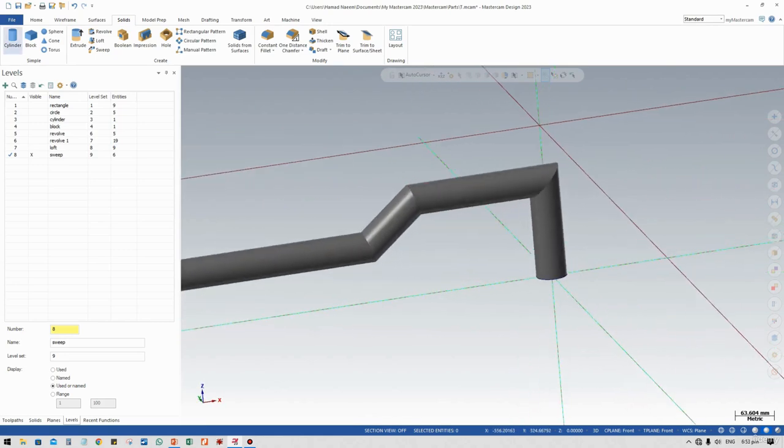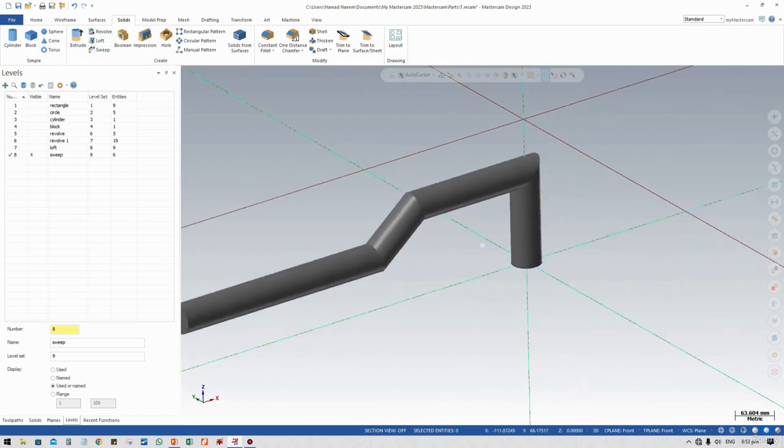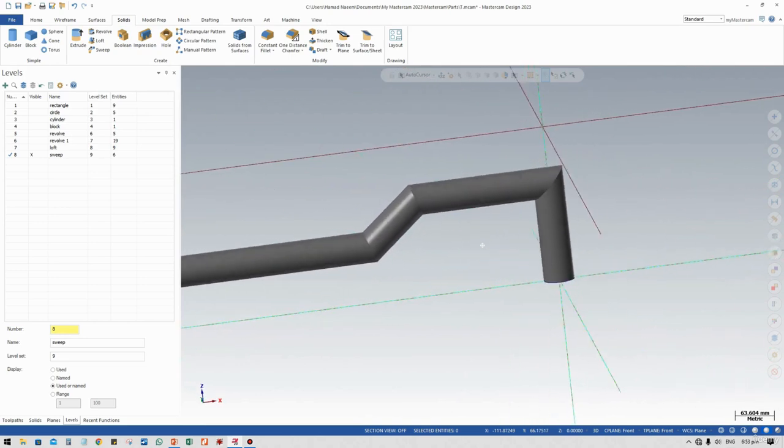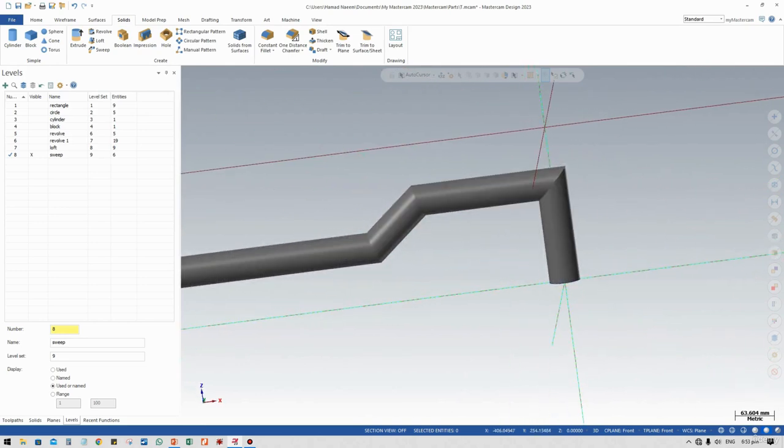So we discussed this simple cylinder, the block, the extrude command for creating. First we create the 2D wireframe, and then we apply the extrude command and cover the extrude body and cut command. And then we cover the revolve, loft and zip command. So this is how we can perform different commands in the solid tab, and we apply the fillet and the chamfer.